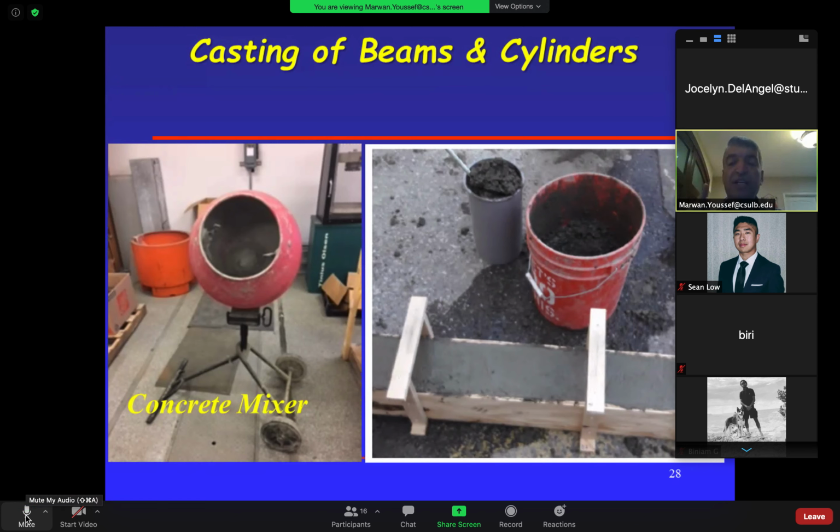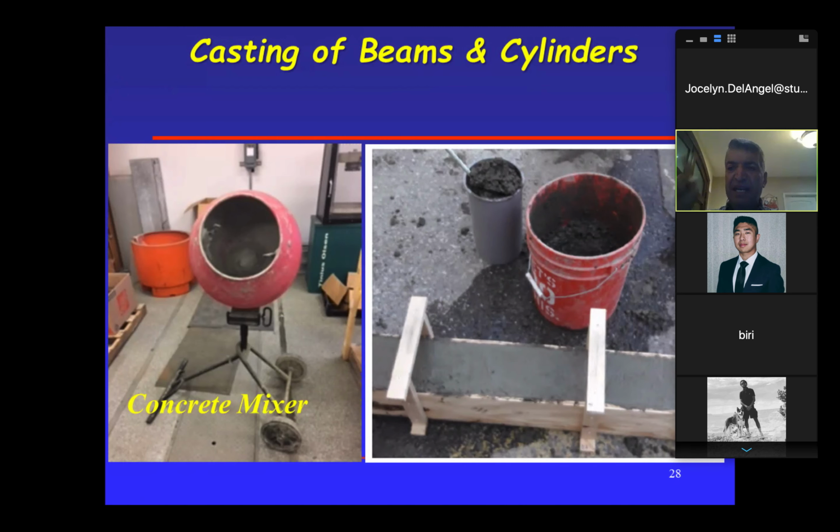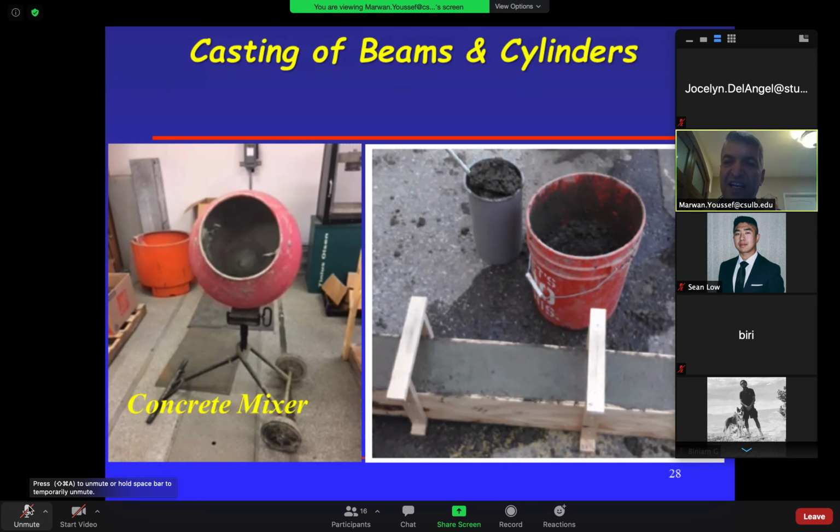Oh, that makes sense. Once they get to the job site, then they put it on a higher speed and mix it more. Now, the only thing as an engineer, you need to be careful and don't let the driver add more water to it, because there is a spray hose. They can spray water into there.